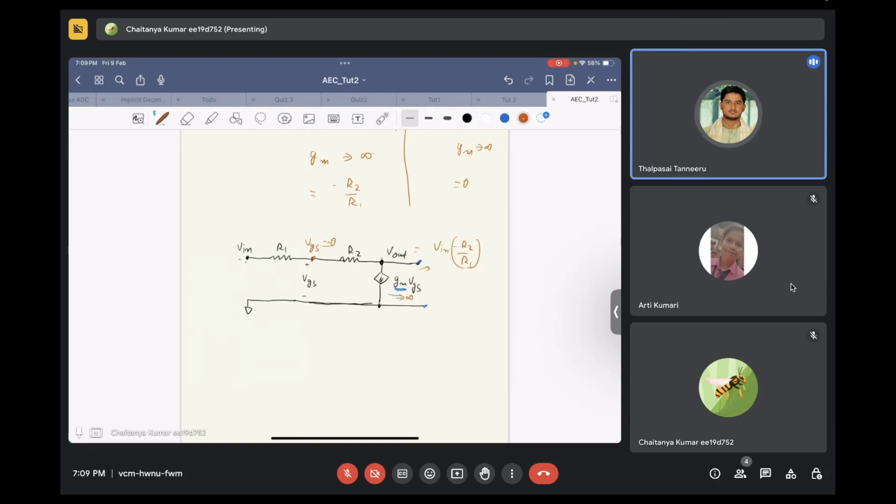Ideal, sir. Okay, the op amp is ideal, but when will virtual ground actually occur? Let's say I have an op amp with a plus and a minus terminal. Will there be virtual ground between the positive terminal and negative terminal in this configuration? Oh, no, sir. When there is feedback resistance, and which kind of feedback? Negative, inverting. Okay, negative feedback.